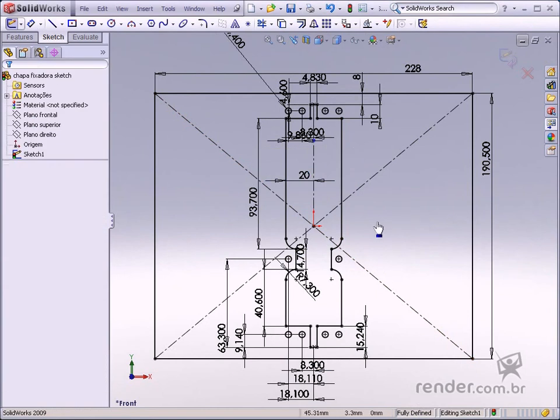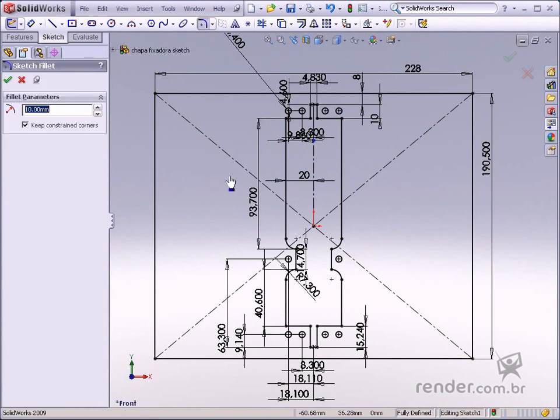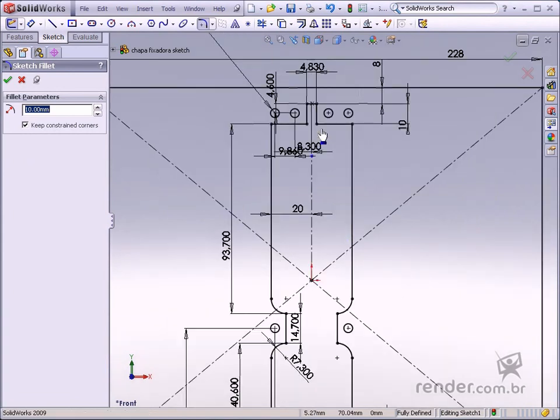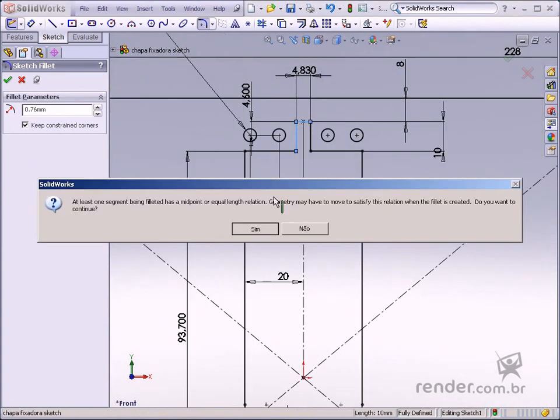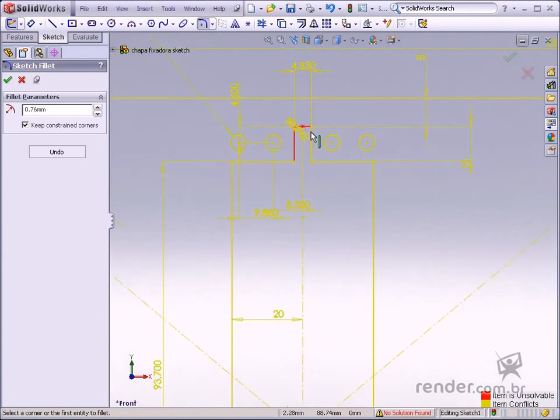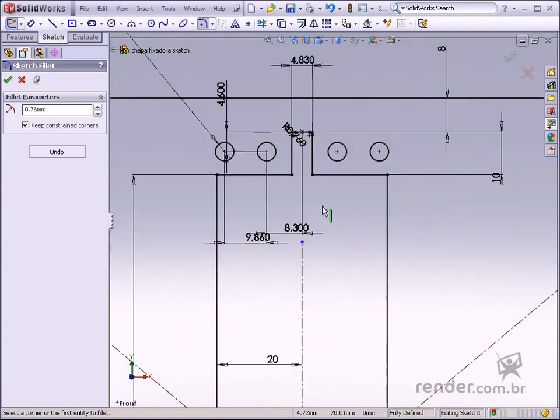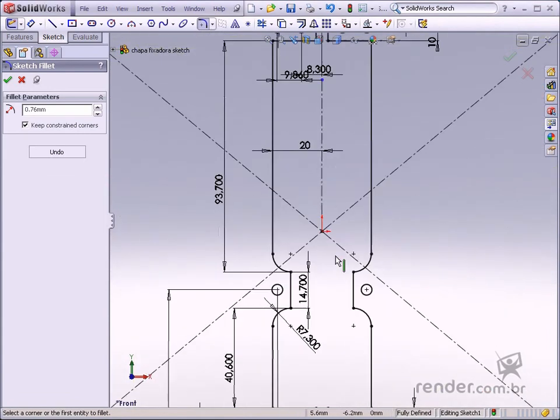And let's check the geometry finishing touches, and we'll insert some fillets on some corners and learn about applying the chamfer command. Enable the fillet command as shown, define the fillet radius and start the selection process. There are two ways to select without escaping from the command for inserting different size fillets.